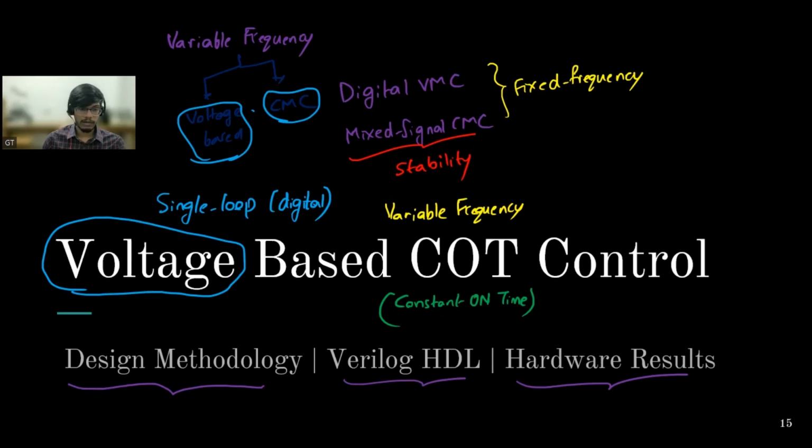When we are talking about the loop, we have the information about capacitor voltage as well as inductor current. We are regulating it at a voltage V0, but how much current is being drawn depends upon the load. It can be 1 ampere, 10 ampere. At 1 ampere, we'll have the peak or valley corresponding to 1 ampere.